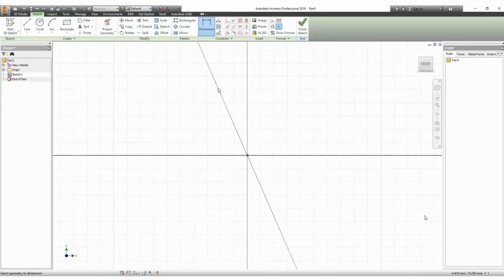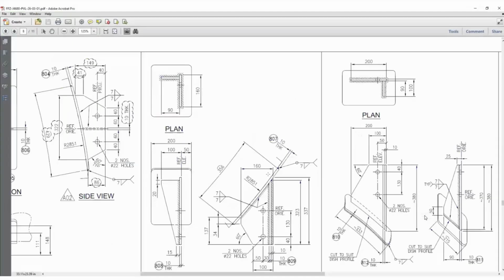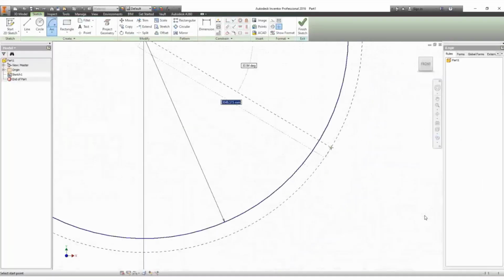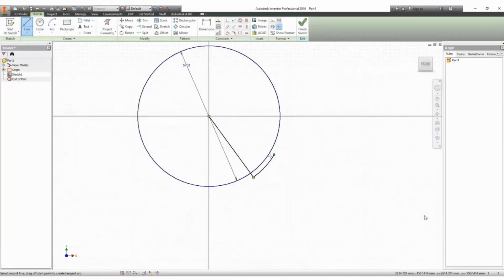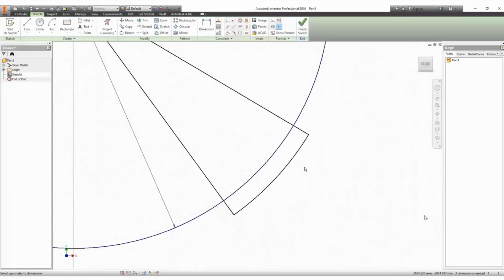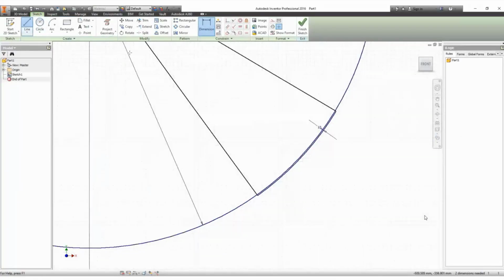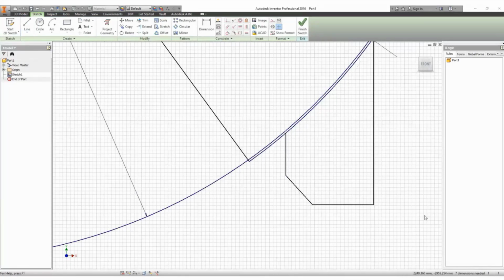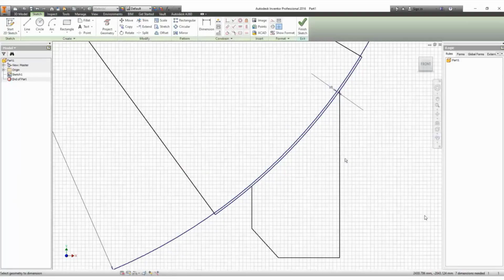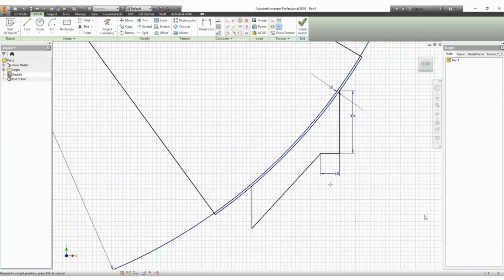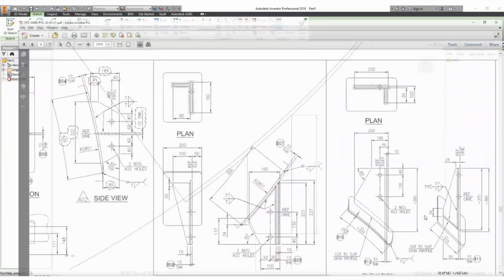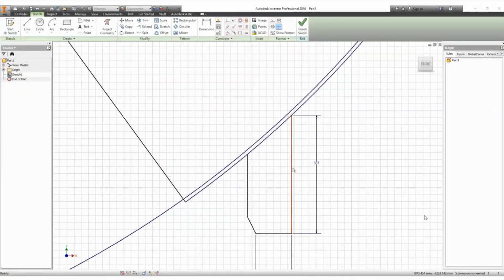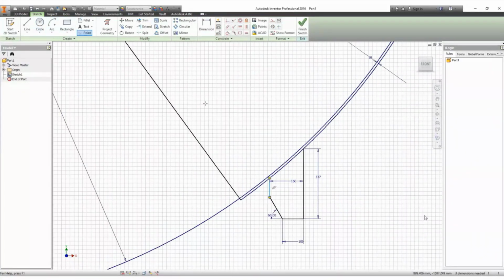We will use the 3D modeling features of Autodesk Inventor to create this part. So we will make 2D sketches to identify each part's dimensions. Like here for the wear plate, we define the wear plate thickness. After that, we will make the support clip and modify the dimensions of this clip, like the height, the bottom width, and the top width, which is 160, like that. After that, the tilted angle for this line.